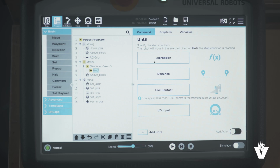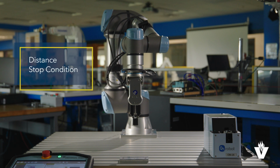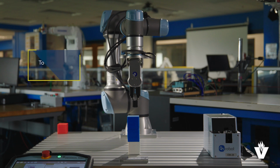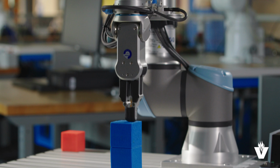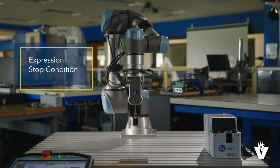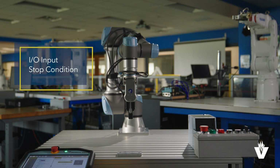There are 4 types of criteria for stopping while using an until node. Distance. This node can be used to stop a direction when the robot has moved a certain distance. The velocity is ramped down so the robot stops exactly at that distance. Tool contact. You can use this node to stop a movement when the robot tool detects a contact. Expression. This node can be used to stop motion due to a custom program expression. You can use IOs, variables, or script functions to specify the stop condition. IO input. You can use this node to stop a signal-controlled motion with an IO input.